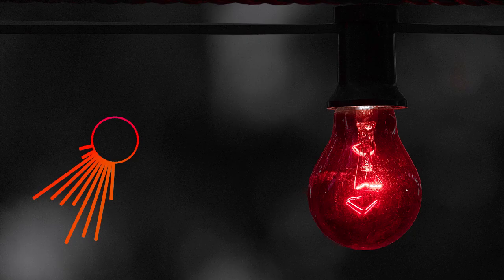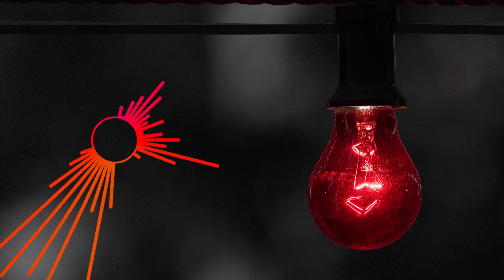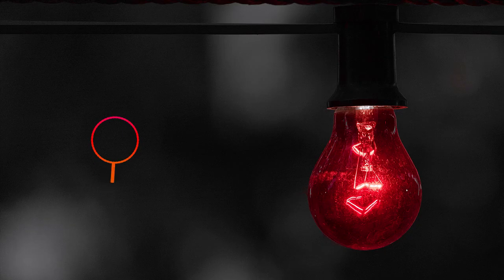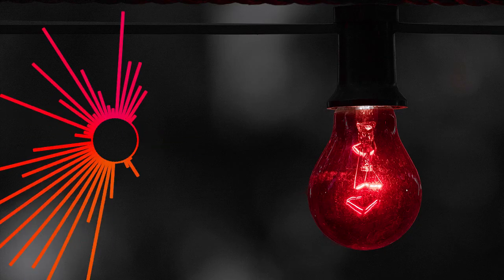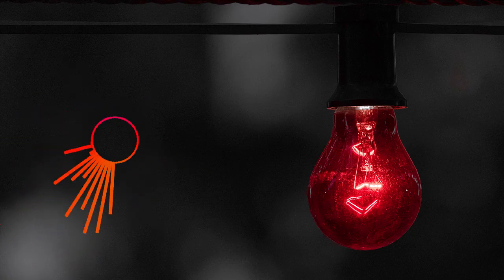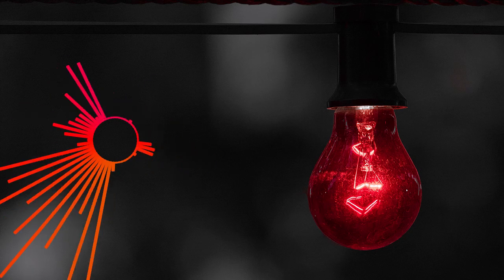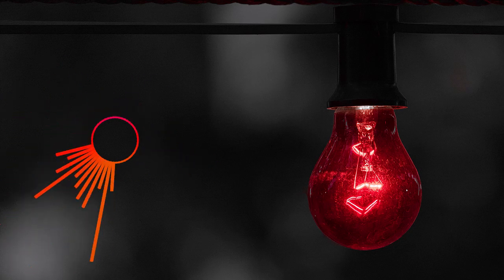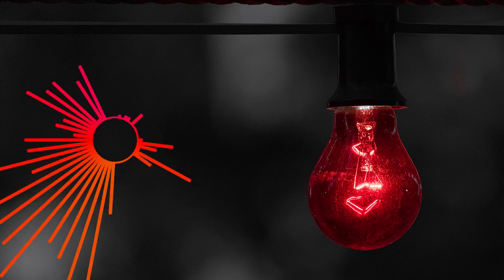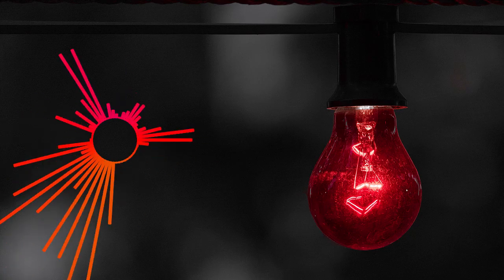Second, we have the fluorescent, the classic tube light. You've probably seen fluorescent tubes in office buildings, stores, and garages. Fluorescent lighting works by using a process called fluorescence. Electricity flows through a gas inside a tube, causing it to give off ultraviolet energy. That UV light hits the white powder coating called phosphor inside the tube, and the phosphor glows, producing visible light.